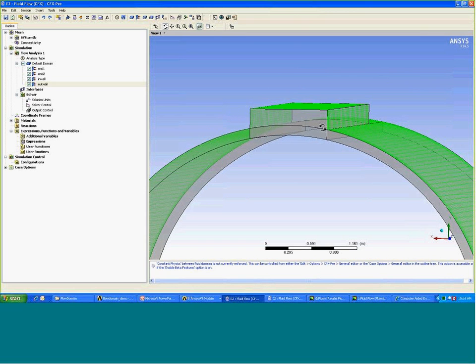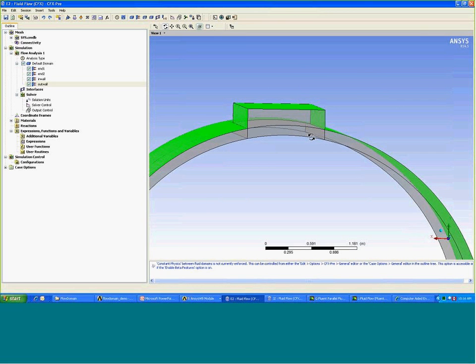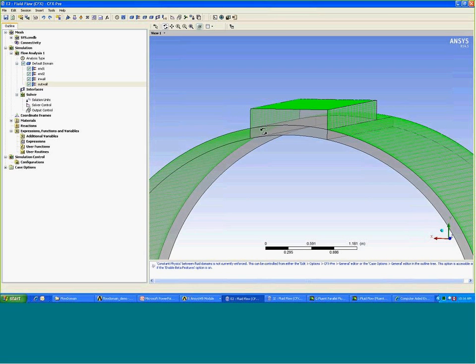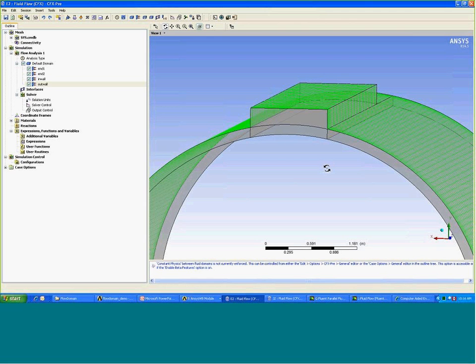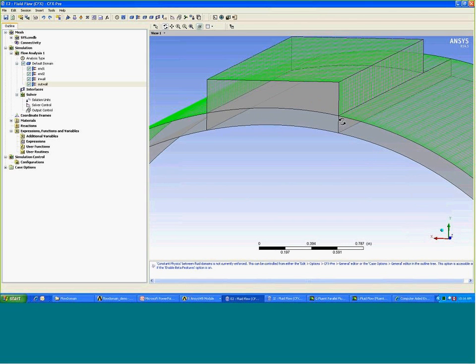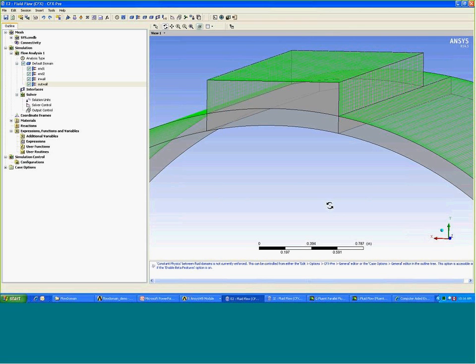So in those regions, like this surface and that one, these are where the three flow volumes come into contact. Because of the flow-through mesh and these three volumes being in a single part, CFX-Pre would treat those as internal nodes. So there's no additional specification that is required for this situation. That's one big advantage.